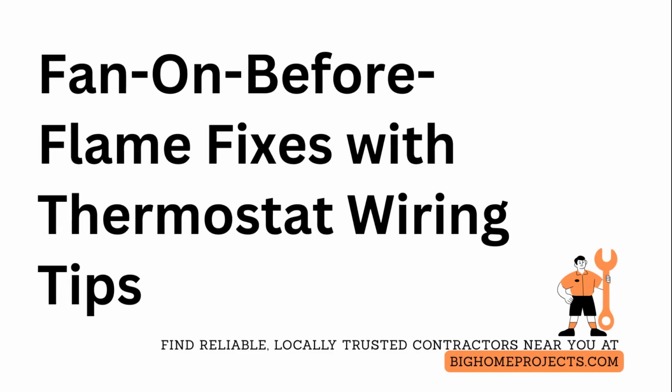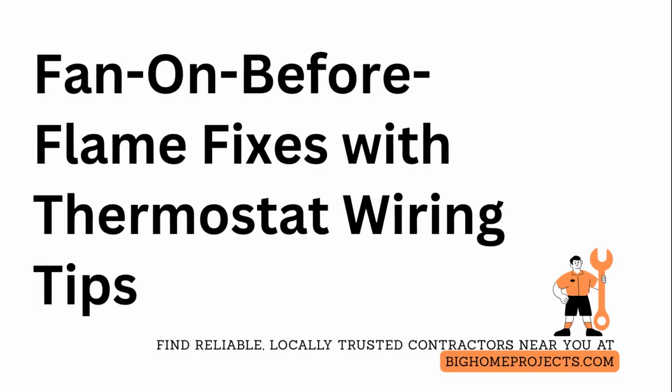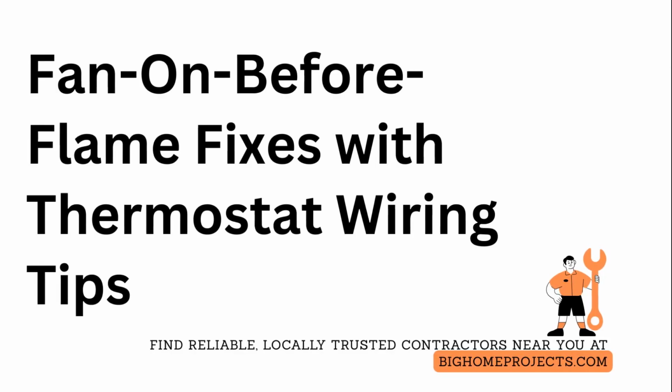Blower fan starting before the burner's heat. The heat exchanger can push cool air into your home, lower heating efficiency, and indicate a control sequencing or sensor problem that needs prompt correction.